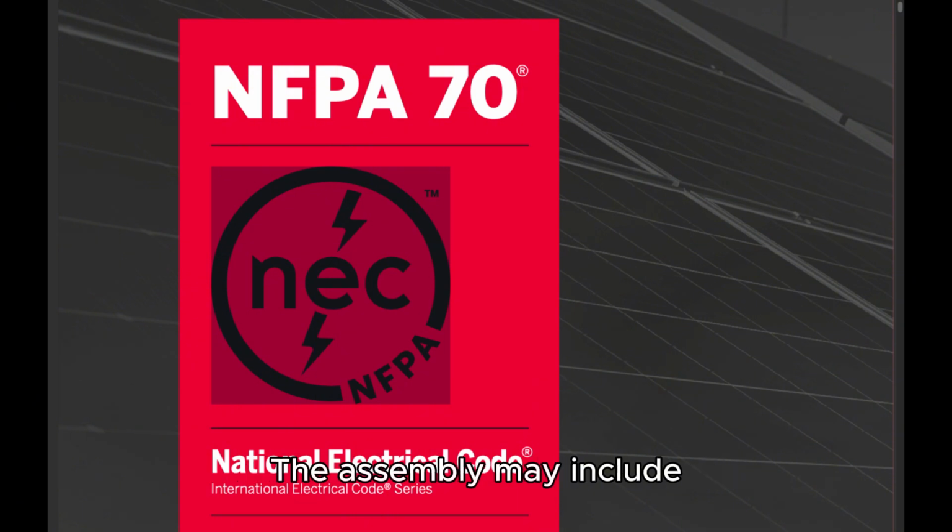The assembly may include control and auxiliary devices. Access to the interior of the enclosure is provided by doors, removable covers, or both. CMP9 thermal protector as applied to motors. A protective device for assembly as an integral part of a motor or motor compressor that, when properly applied, protects the motor against dangerous overheating due to overload and failure to start.